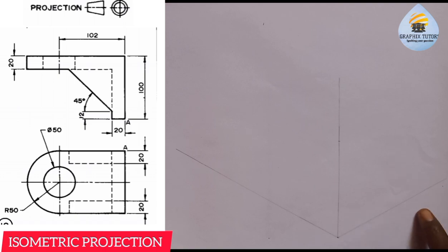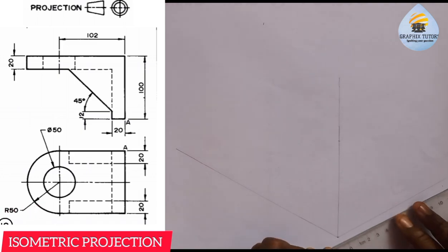That is the thickness here, which is from this point. You get it from the plan, from this end to this end. And that will be the diameter of this circle here, which will be 100. How did I get that? Radius of 50 times 2 gives you the diameter, and that is 100 also. So I'm going to measure 100 here.